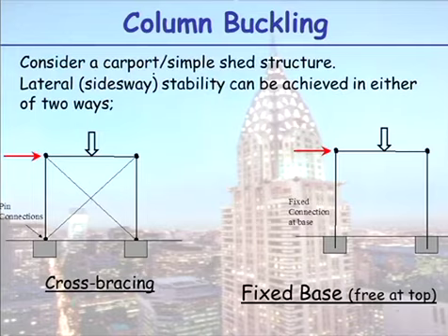Cross bracing is the easiest way to stabilise a structure. When you go out driving and you see those hay sheds and they're all leaning a bit, well, they haven't got any bracing in their foundations, they're all leaning over. To create a stable structure, you need to ensure no side sway, and the easiest way to achieve that is to put cross bracing in your structure, and it's usually hidden in the walls of the structure, or the actual cladding you put on provides that stability.